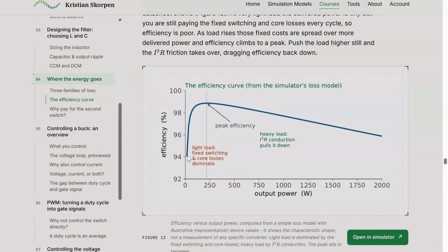In the beginning, it rises very quickly, because the efficiency is very low due to the magnetic losses, while it starts to decrease afterwards because the conduction losses increase. And that is why we get a peak efficiency at a relatively low point. And you can design this buck converter to have a peak efficiency wherever you want.